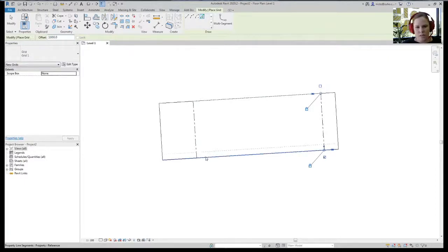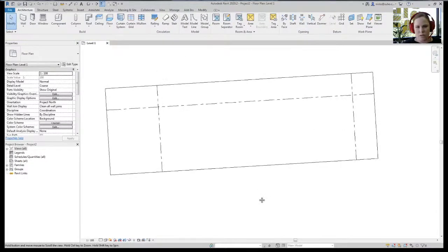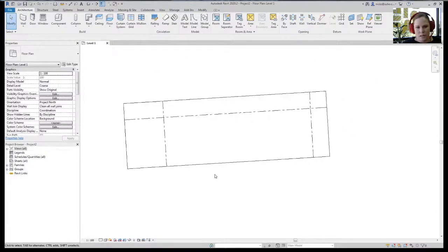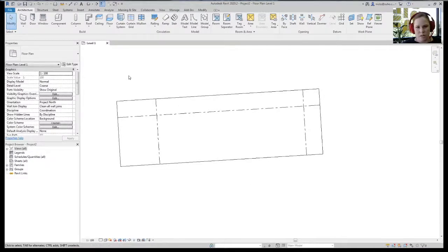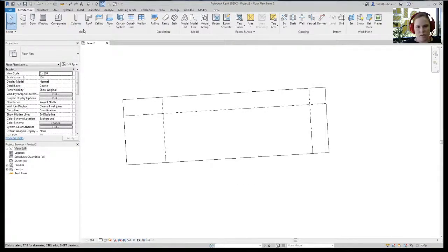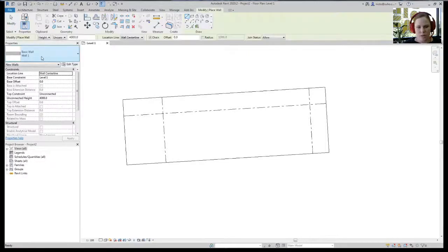What's interesting on these particular sites up at Woodford is the 1 metre either side of the building that a lot of the development has actually adopted. In our instance, and the example I'm going to show you, we actually used the southern boundary as a common wall because we owned the site next door, and we actually put the building further back so that we could get more north light in. So you can imagine if you have lots of these little developments close together and you've only got a metre either side of you and the boundary, you're not going to get much light in.